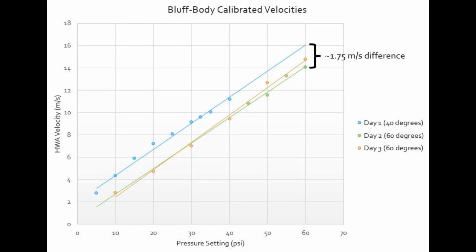When I perform flame analysis, I will not immediately have a calibration curve at that day's temperature, so I will need to conduct hot wire at the beginning of that day to find the pressure settings for 5, 10, and 15 meters per second. This process would add about 20 to 30 minutes, but it would allow me to develop a master data set over that time that would then create a calibration for all the daily temperatures.